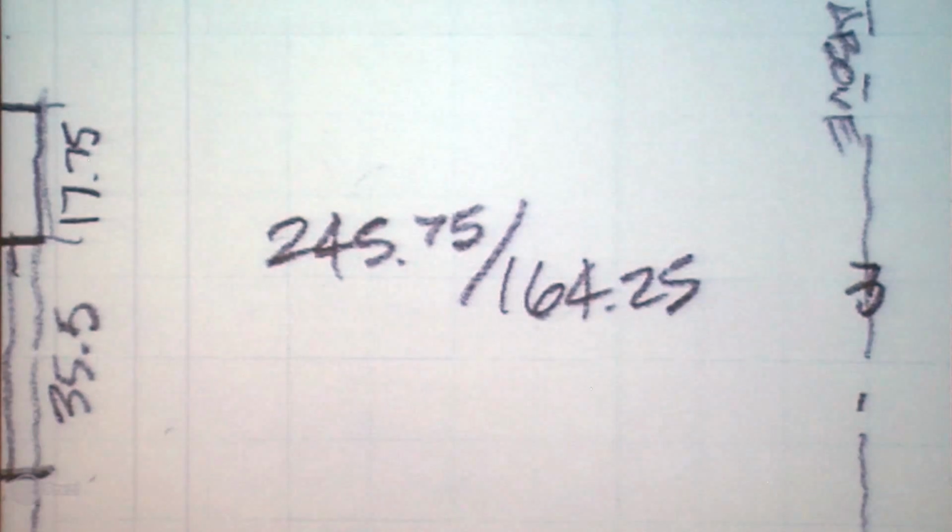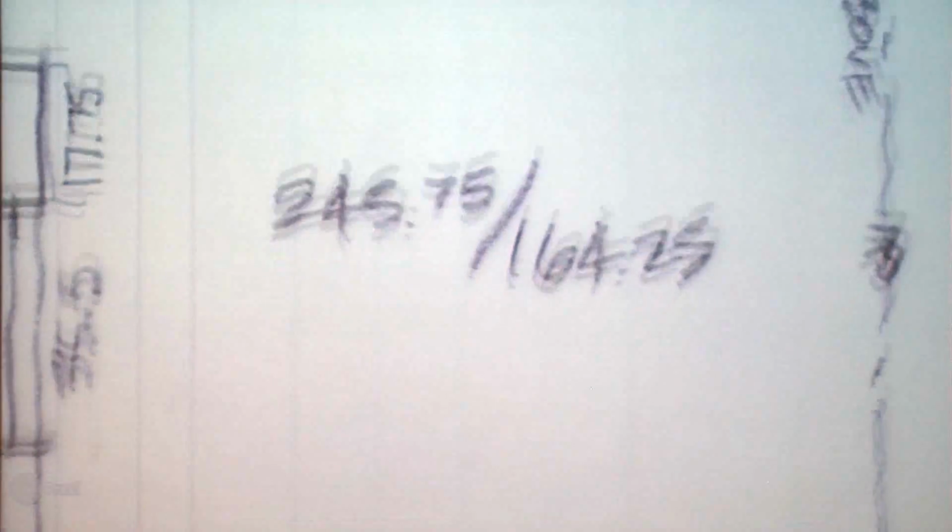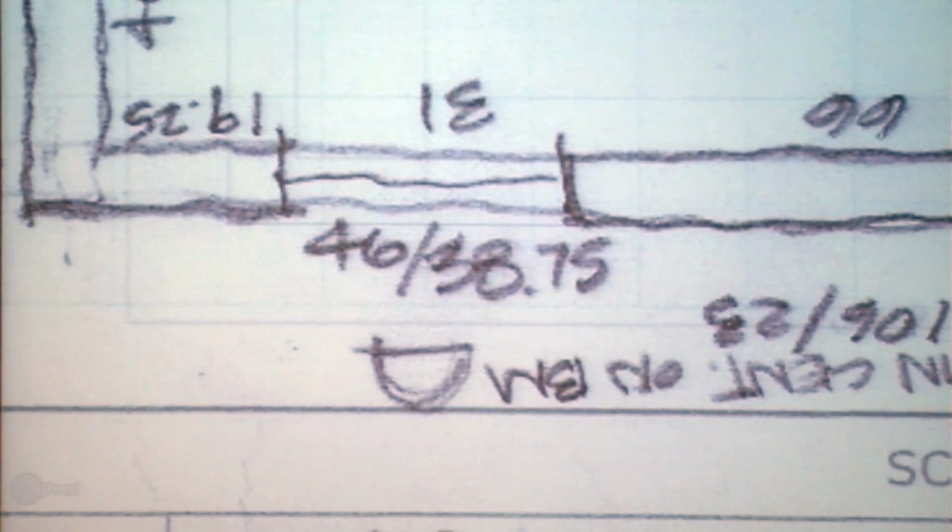So the way that we record field notes, if I zoom in, I always take an X and a Y, like an overall room dimension. And that's just kind of a check, just in case. Like if things aren't adding up, I've at least got somewhere to check. Also, our windows, we record them as sill height, window height. This way, as I'm drawing my existing conditions model, I'm able to very easily copy my openings up by 46 inches and 38.75. The reason for all of these field notes and the way we're recording them is that end goal of modeling in SketchUp.